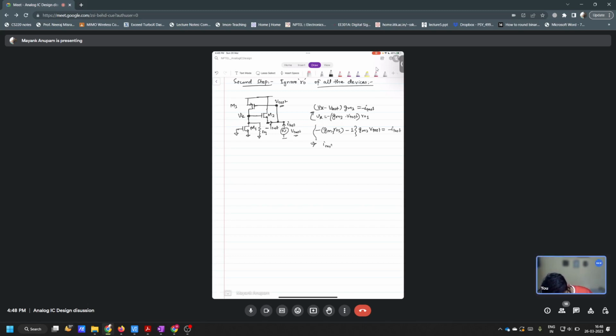Yeah, and what will it be? So it is I test by V test, or let's do the other way around. V test upon I test is equal to what? 1 over Gm2, divided by 1 plus Gm3 times RO1, isn't it? So you were saying it is only 1 over Gm2, right? But it is much more than that, isn't it? Much less than that. It is much less than that, isn't it?